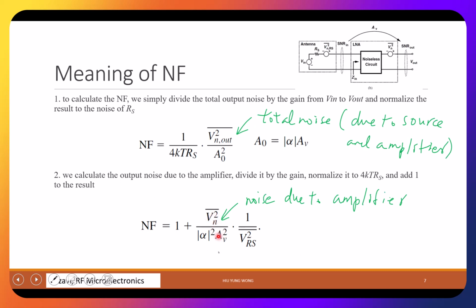Correct, but noise figure again is just a human defined factor, right? This input noise really depends on the characteristic impedance. You need to have an impedance in your circuit. It cannot be 0, and usually it's 50 ohm.